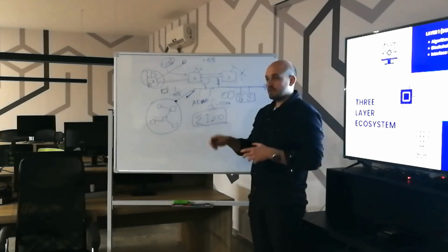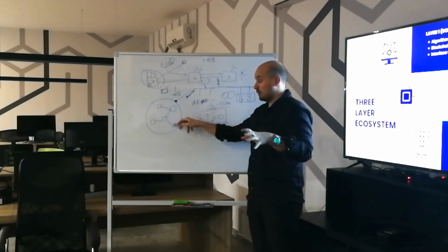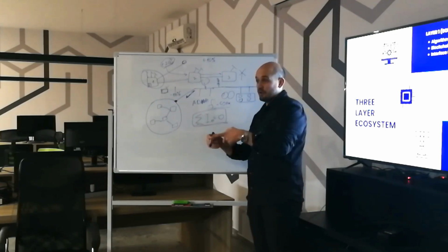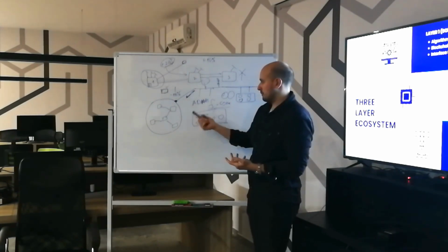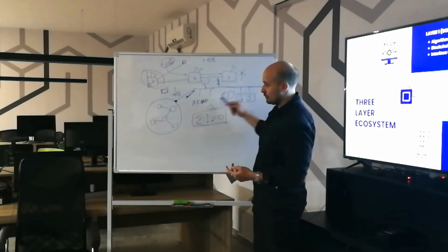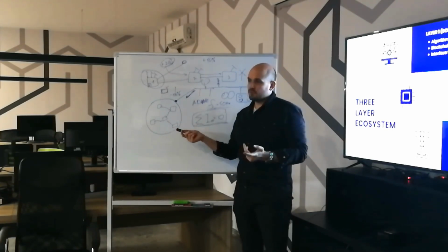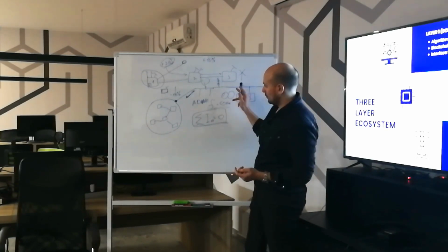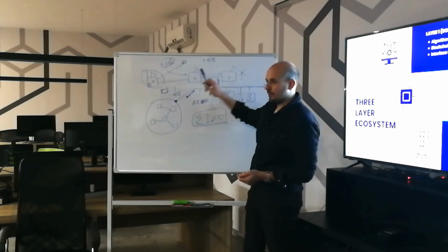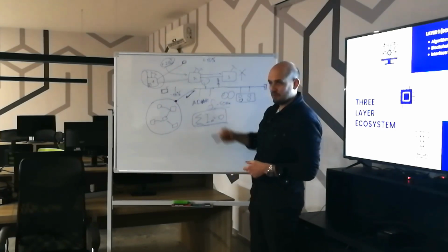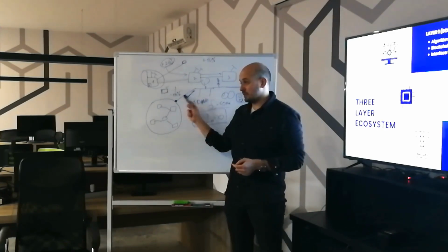We've seen through the research that bigger microgrids that have 50 or 100 households inside of them can actually offer energy balancing functionality for the main grid operators, and they can actually earn from that. The reason for that is that it's cheaper for the central grid operator to export the excess energy to the neighboring household than to export it to Hungary, for example, or Switzerland. And this is why connection with the central grid is very, very important.